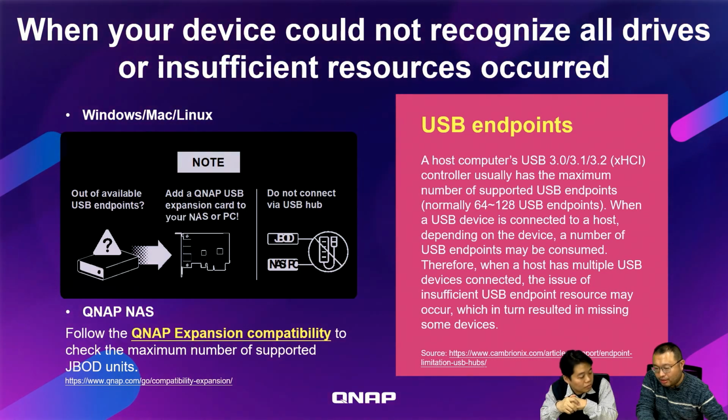Even though it's a single device, inside it consumes many USB endpoints. So if you connect multiple ones, you may reach the limitation of your USB controller.